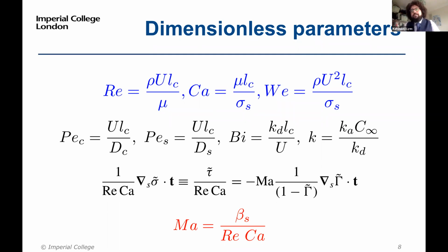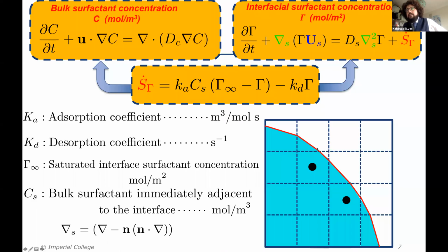This is all the type of input parameters you use with your simulation, and the output when you run any simulation, I'd say, is the Marangoni stress. And the way we define this, we go back to this equation of state, and then when we derive, you have a variation of sigma, and this gradient will give you what we call the Marangoni stress.